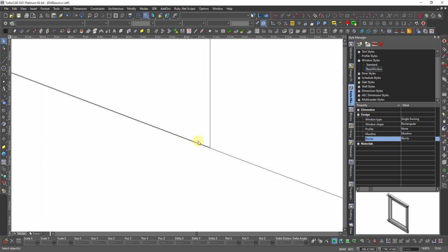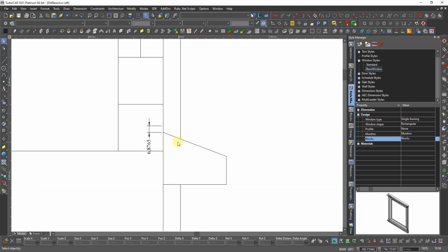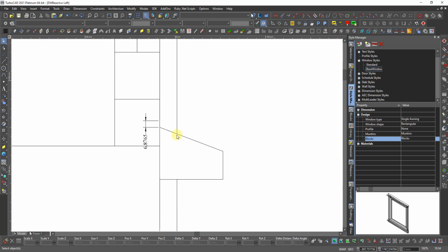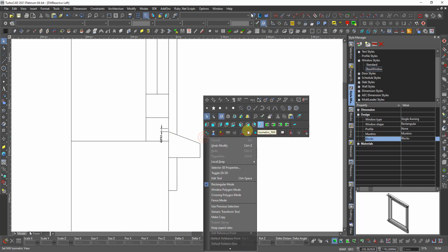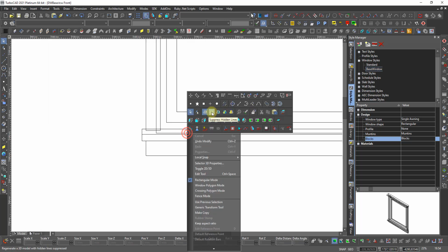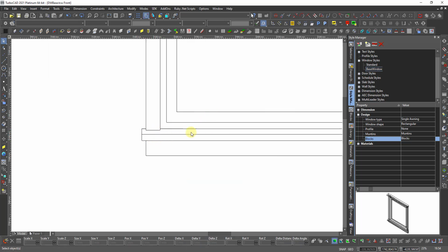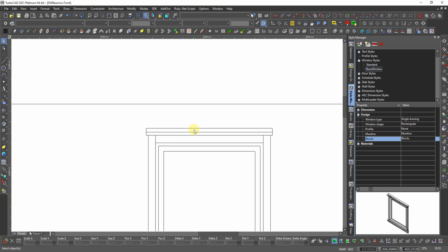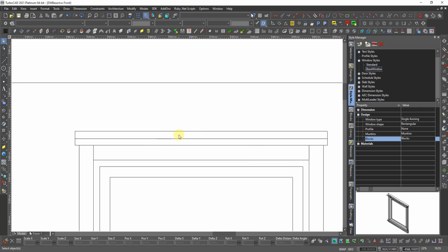Now they are close. A little gap there, but that's only good. If we have more decimals, it could be more correct also. But I like there's a little gap there. That's because if you now see the world from the front, and I go to hidden line, I can see that line. And that's the point. I can also see the line here at the waterboard, and that's nice. And I can also see it here. A way to cheat on this is to take it out 0.1 millimeter or something, so it doesn't melt together with the wall.